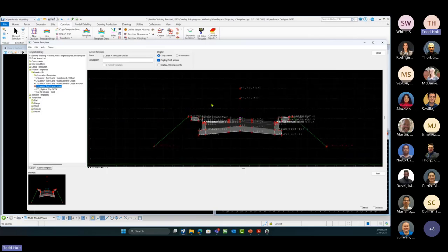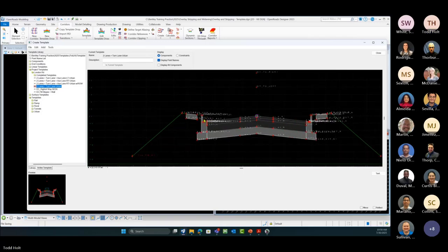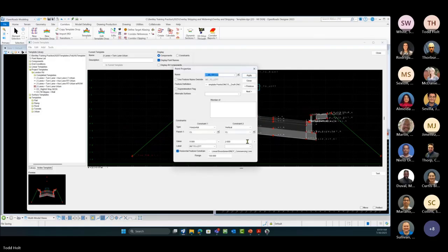So on this particular situation, we might have an intersection to the left. So this just has a null point up above. So this point is set 2 feet above. We're using a parametric label on this, so intersection to the left.